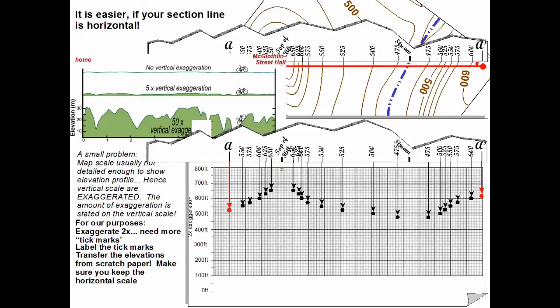Let's put the top of the hill in place, which should be the highest point, between my 2 contour lines, and also the stream as the lowest point. All that is left now is to connect the dots. Again, don't use straight lines, but try to have a curve so it represents what nature really would look like. Voila! We got our profile now identified, and that is the surface as you would see it.